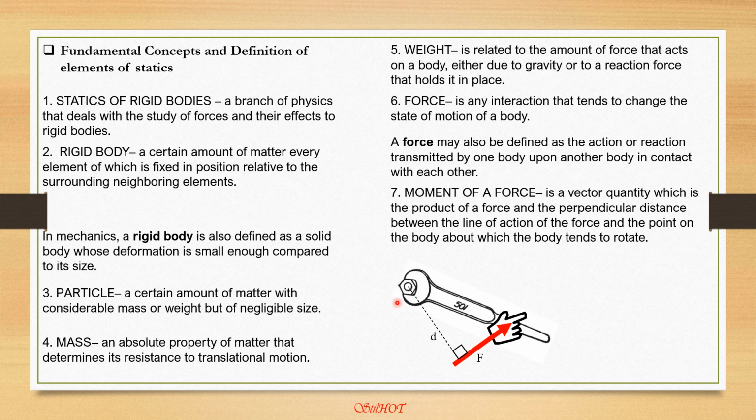So we will call the moment arm as D and the moment center as O. It has a sense. It is either clockwise or counterclockwise, but for this case it is counterclockwise, which is positive in statics. So when the force is applied, this moment arm D tends to rotate counterclockwise. So the sense of rotation of the force is the tendency of this moment arm to rotate about this point O here, the moment center.